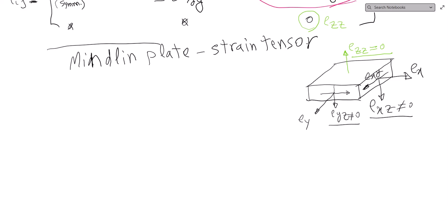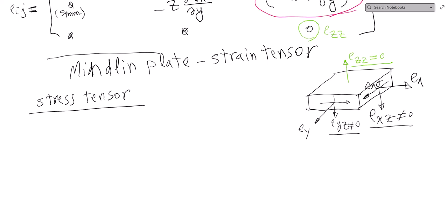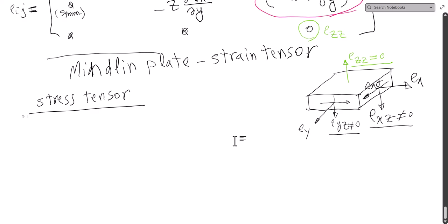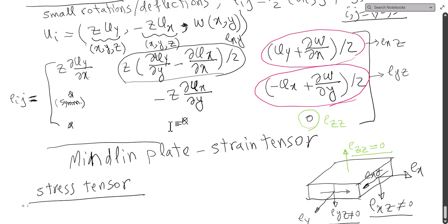Let's go to the stresses. Now, the same discussion that we had in Kirchhoff-Love theory, and I summarize it here, but for the full discussion, please refer to that series, is this: if you go after a 3D elasticity constitutive relation, or shall we say 3D Hooke's law, relating stresses to strain, and I calculate the stresses, you will run into issues for satisfying boundary conditions or surface traction compatibility, and so on and so forth.